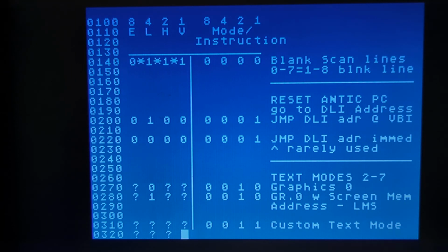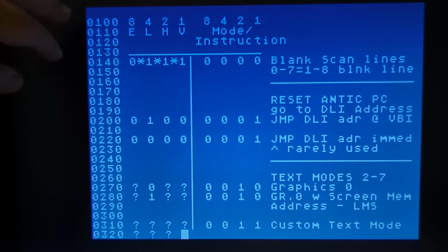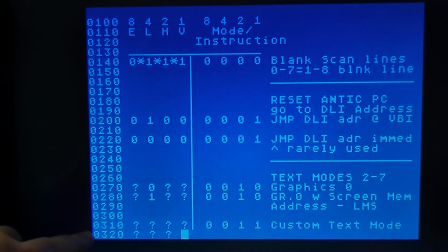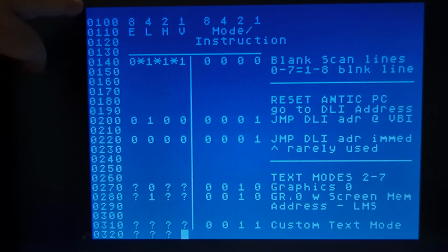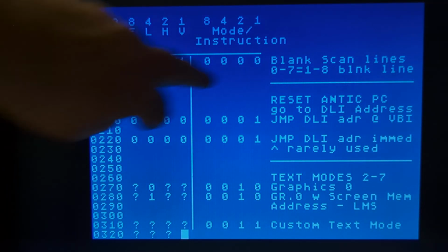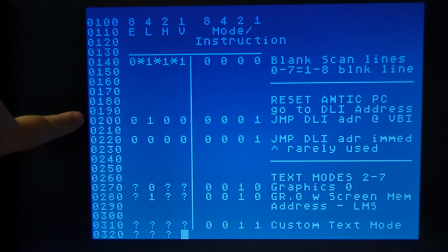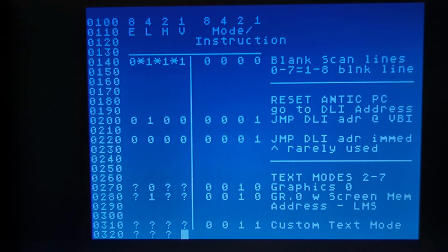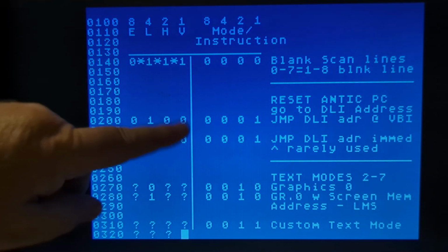Each instruction in the ANTIC chip can take up a different number of scan lines, but of the visible ones here outside this border, there's 192. There's some above here, and there's some below here, and there's 160 across, and there's some that come before here, and some that come after over there. But the visible ones, it's 192 by 160.